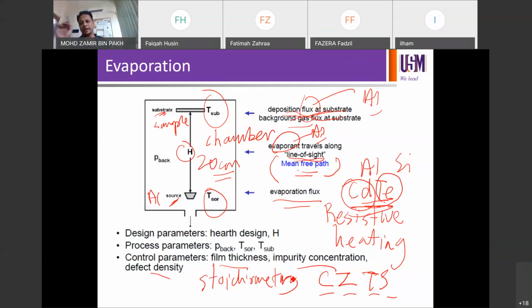You want to have exactly the precursor material, but you don't end up exactly as the precursor material, because when you do the melting process, some bonds are broken, then they could be traveling at different pace with different speed, and they have different collision rate, something like that maybe. Then they end up as a slightly different compound on the substrate. So this is called the stoichiometry problem.